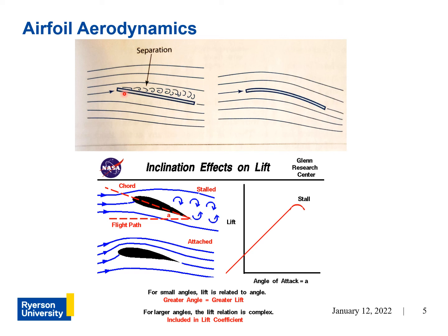But if you increase its angle of attack high enough, it'll easily separate the flow of air around it. So the flow of air is no longer attached, and that's what you call the stall condition. And again, flow separation causes a disturbance in the airflow, resulting in a reduction in lift and a large increase in pressure drag.